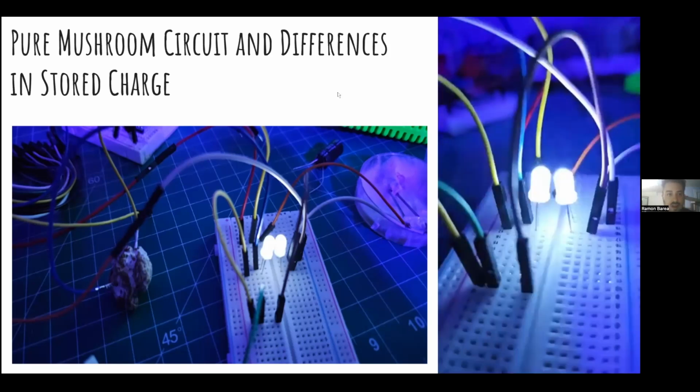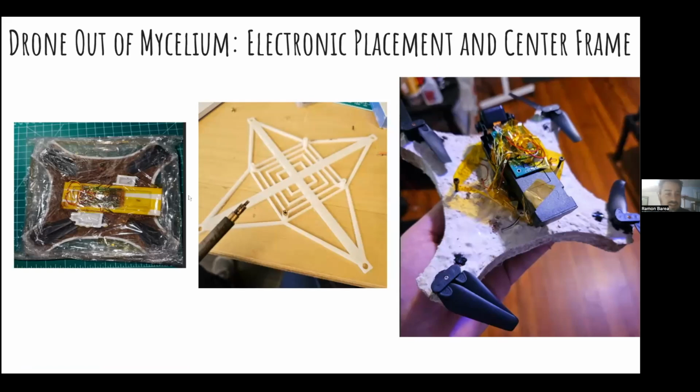And drone made out of mycelium, one of my final concepts. What we had done here was pack mycelium into essentially a PLA molding, and we had to pack the propellers within the molding and leave it over time. It sat about 5-6 days and then was baked at 170 degrees for about 7 hours.